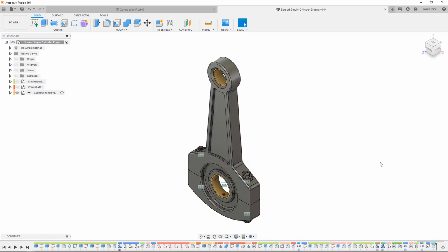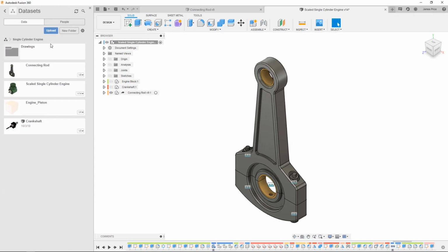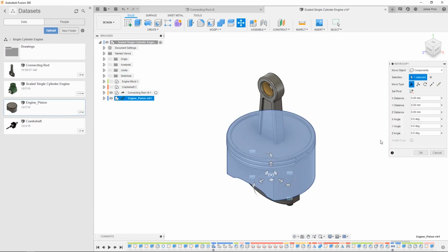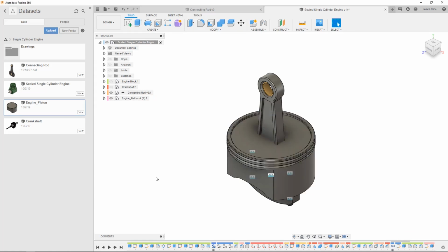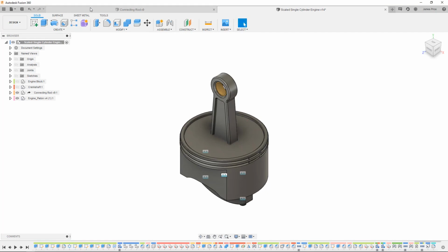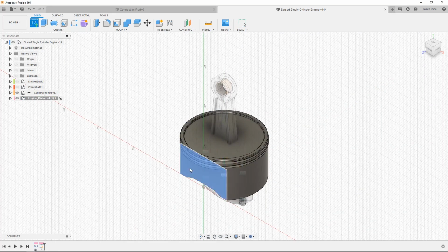I've already created a base outline of our piston, so I will insert, then break the link to make it editable. And to finish, I need to create a piston pin boss for our piston pin, which ultimately is respective of our connecting rod bushing diameter. To ensure the diameter of this boss matches the ID of the connecting rod bushing, I can simply sketch on the face and use the derived parameter from the con rod subassembly.